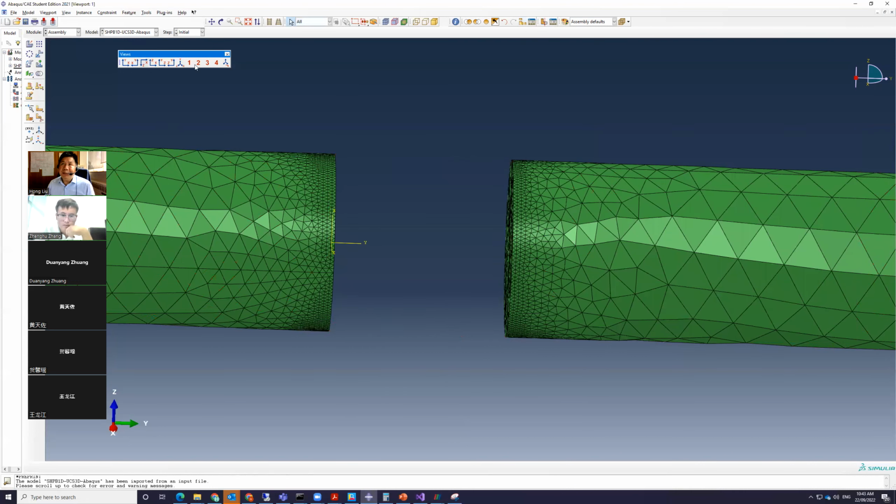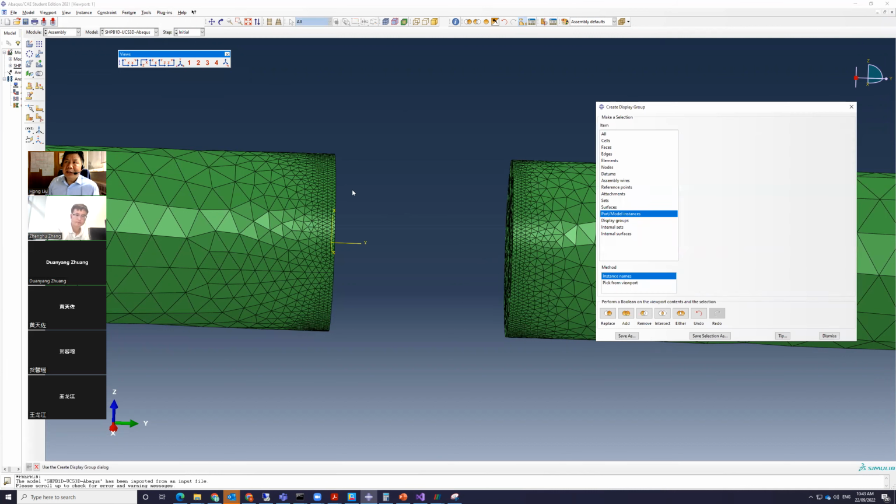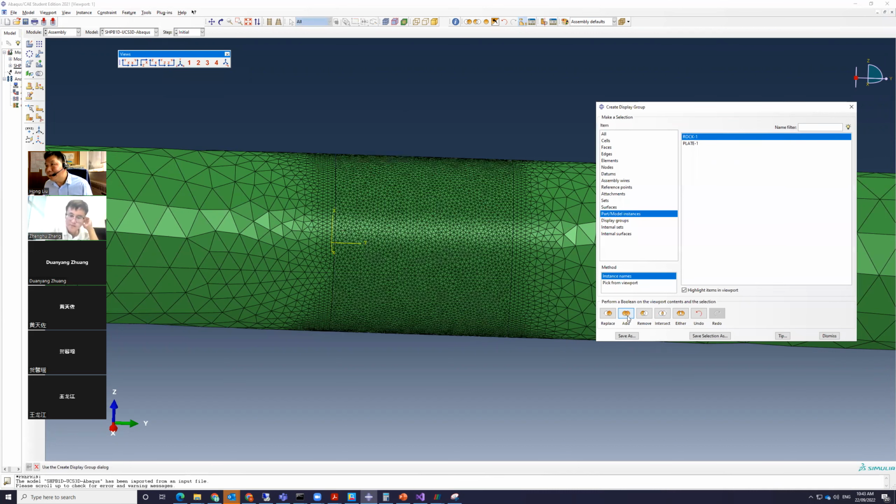You can see for the Hopkinson bar, for all of the locations we use quite a coarse mesh, but around the contact we use the dense mesh. Why do we need to use the dense mesh? What I suggest for this one is to use meshes of almost the same density on both sides. Okay, let me add this back.